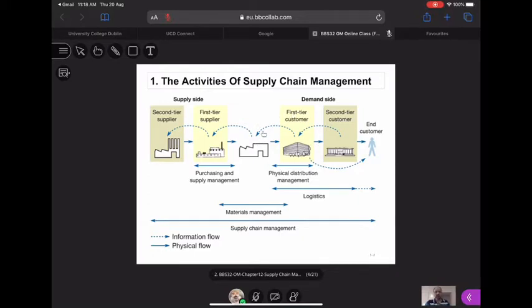So this manufacturer also orders just nice from the first tier supplier, and this raw material producer also produces just nice. So guys, in this pull method, this dotted line is the flow of information. This solid line is the flow of physical product. So you find that information is given here. Then this second tier supplier will produce enough raw materials only to send to the first tier supplier. Then they make sure they produce enough just for the manufacturer, and you find that just nice the customer will buy. Of course, there's some buffer, but not too much buffer, so we can reduce our wastages tremendously.